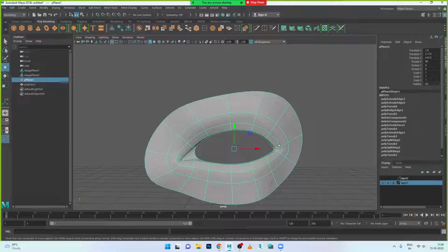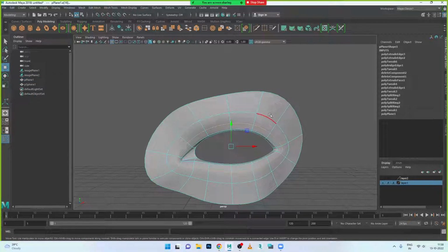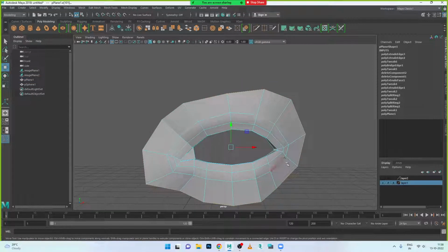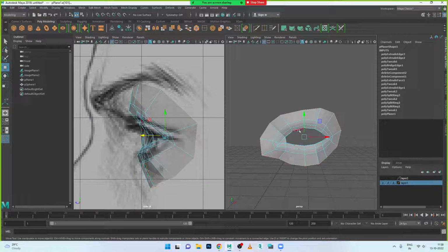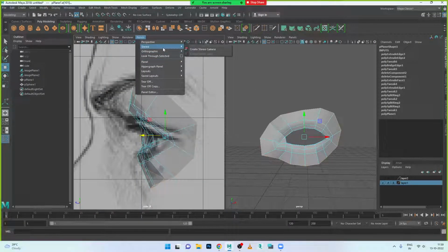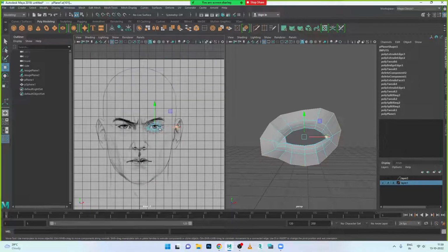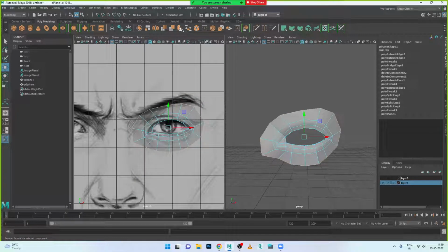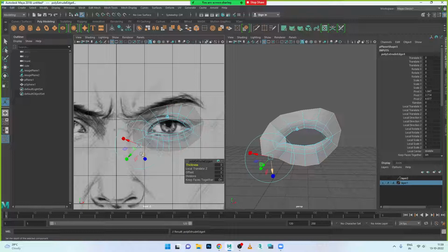Okay, what depth we need? The eyes portion will be here, right? This portion should go a little deeper. So for this one, first of all, what I'll do, I'll go with the edges now. Press 1 key, double click on this all edges again. Use extrude option from the front only. Orthographic front view, zoom. Use extrude option and try to extrude this one again now.